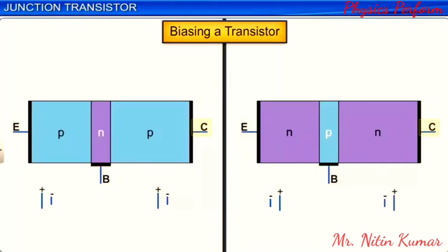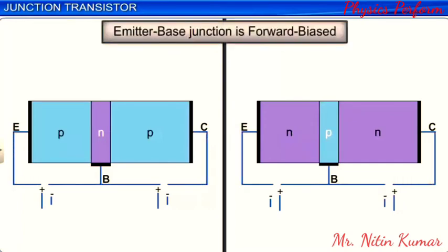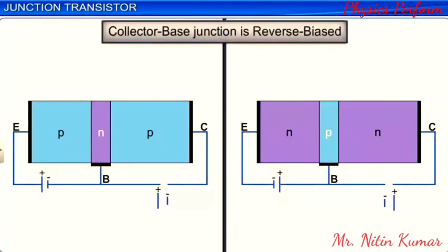In this module, we discuss transistors in common base configuration. During biasing, normally the p-n junction between the emitter and the base is forward biased, while the p-n junction between the base and the collector is reverse biased. The reasons for adopting such a biasing scheme for the two junctions will be discussed at the appropriate juncture in the course. A transistor with its emitter base junction forward biased and base collector junction reverse biased is said to be in an active state.